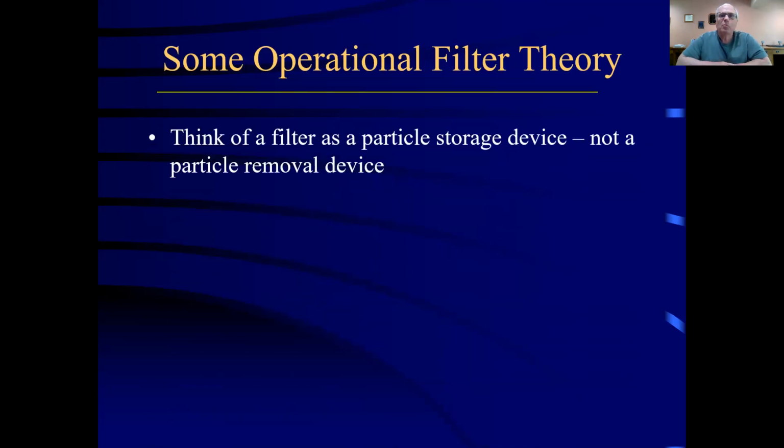Try to think of your filter as a particle storage device, not a particle removal device. While you're running a filter for, say, 60 or 80 or 100 hours, however long you run your filters, it's storing particles that it trapped. But you haven't really removed those particles from the water until you take that filter out of service and backwash it. While it's running, you're just storing particles, and there's always a price to pay for storage.